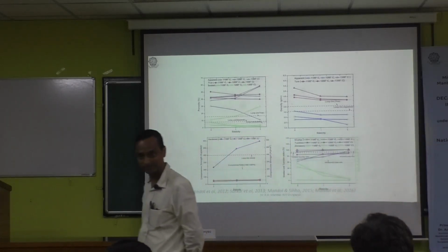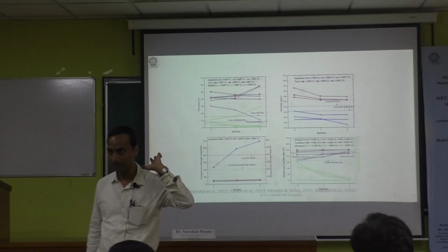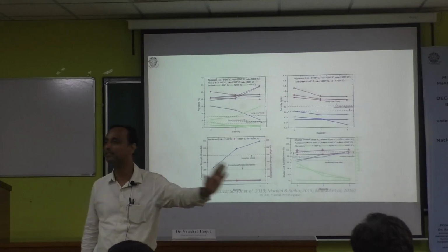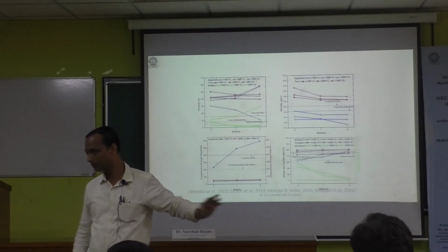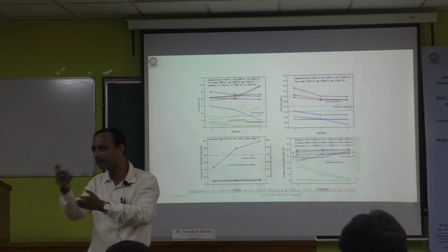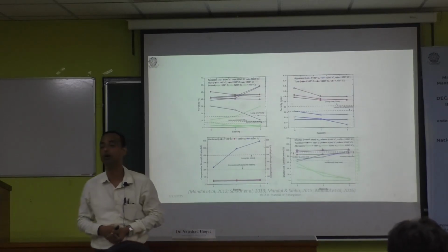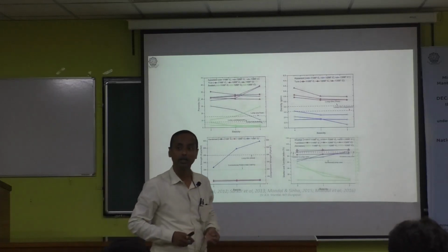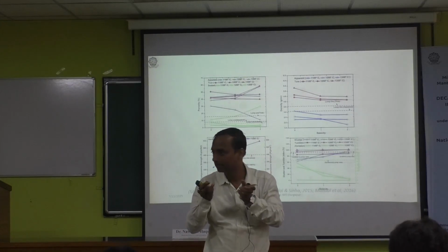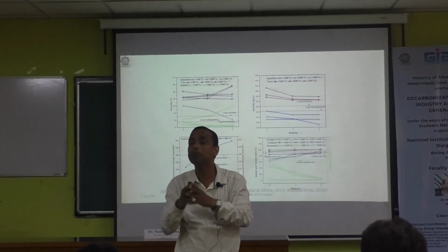Free lime should not be there. The presence of free lime actually makes the pellet hygroscopic. Then you have to make the pellets non-hygroscopic, so that there is no free lime present on the surface. If you can restrict the free lime formation on the surface, then you can prevent the breaking of the pellet. And yes, one mechanism is there. If you increase the temperature and this lime reacts with some other elements so that it becomes a compound, not free lime.